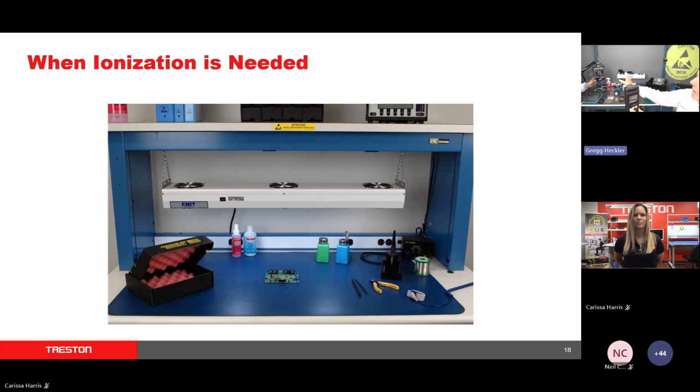Okay, so can you turn it? There we go. Okay, so now, can you see that screen? You can see it's still counting, still counting, still counting. I'm already up to 6 seconds. Now that's not a problem if I set my maximum discharge at 10 seconds, if that's all I need. So you just want to make sure you establish a maximum time that you can meet.